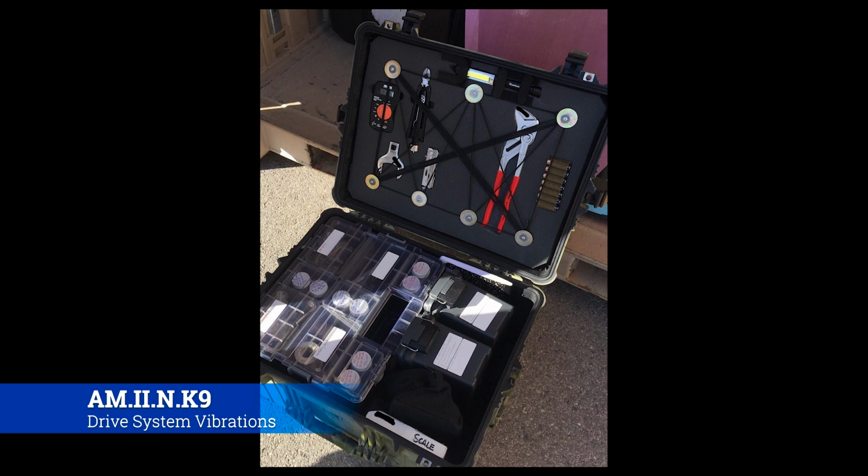Now, why would you need to put on or take off weight from a rotor hub? Well, think about a wash machine. If you take all of the clothes in your wash machine and put them all on one side and leave the other side blank, and you turn the wash machine on, it's going to make a horrendous noise and be shaking all over the place because it's out of balance. However, if you disseminate the clothes to where they're equal all the way around, you turn it on, it'll work just fine. This is no different. It's just that you have more weight, at a higher RPM, and it costs a lot more than your wash machine. So what you want to do is make sure that the rotor blades are balanced out.